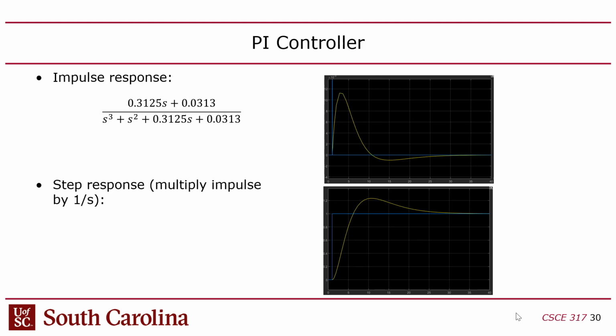Yeah, so here's the step response. So this is like, okay, robot, don't move the coin. Now I want you to move it 1 meter. And so you can see that what the robot will do, the controller, is it'll move the coin, but it overshoots. It goes too far. And then it corrects down and then eventually hits the position. So this works. It's stable.